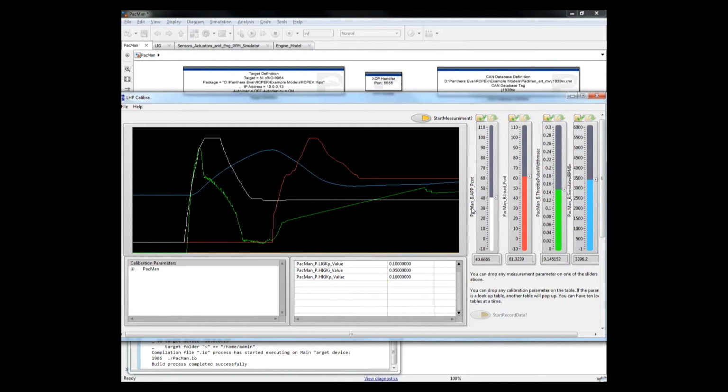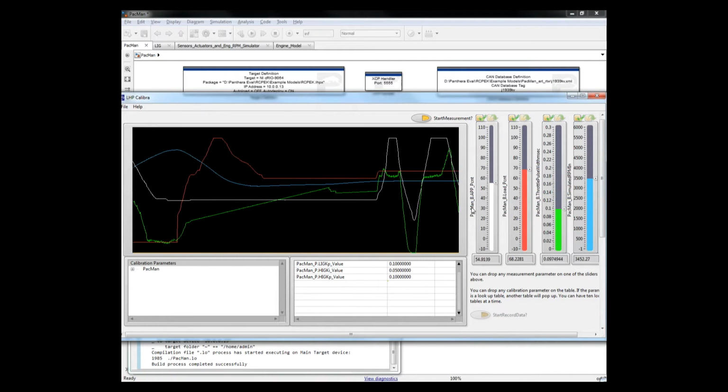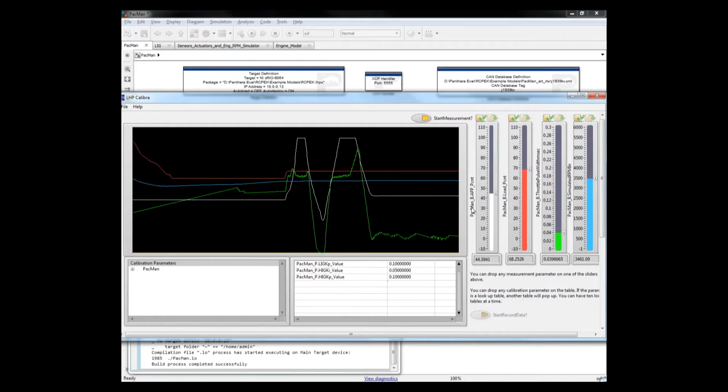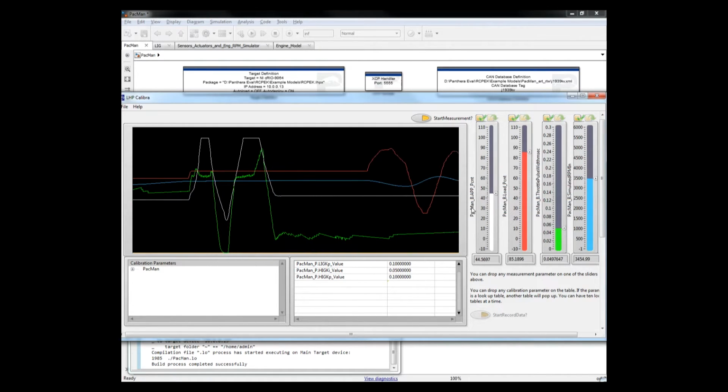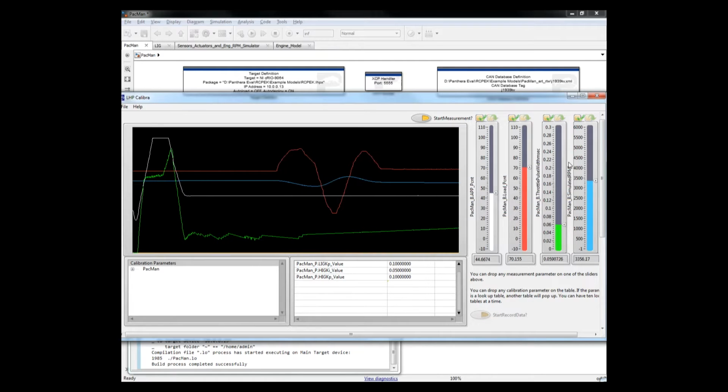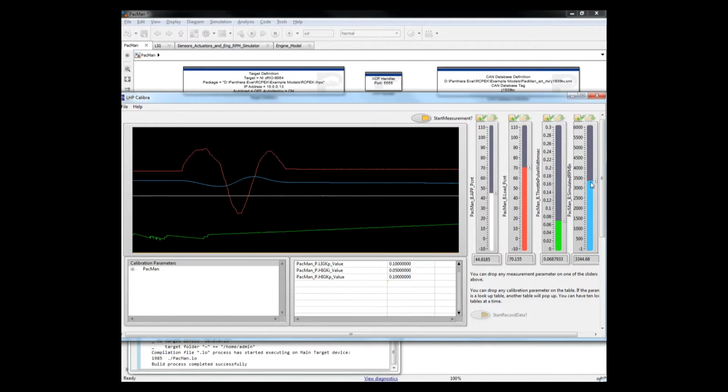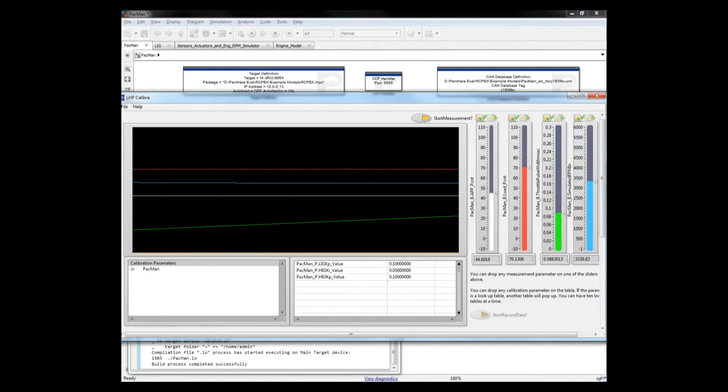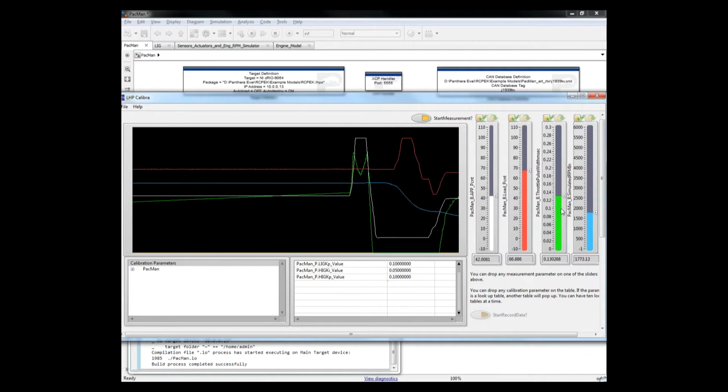And you can see that as I adjust these levers on my device, I could watch my throttle position change. That's the one I'm moving here. I could watch my load change. There's the load, the red one going up and down. And you will see that the throttle valve command as well as the engine speed will follow accordingly. So the 4 sliders that you see here are parameters that you are monitoring on the strip chart. In this case, the throttle input, the load input, the throttle valve command, and the engine speed. I can move those around and the control adapts and responds.